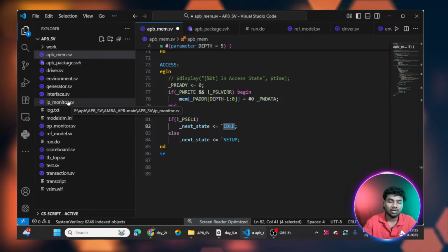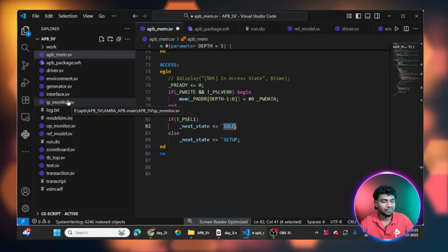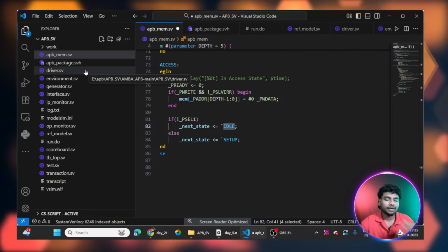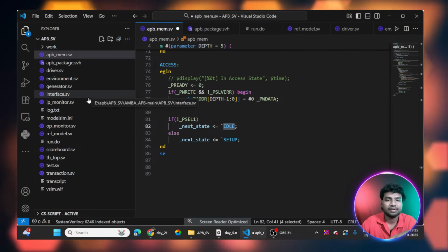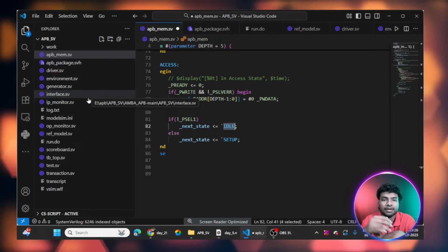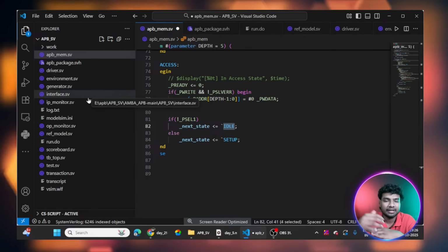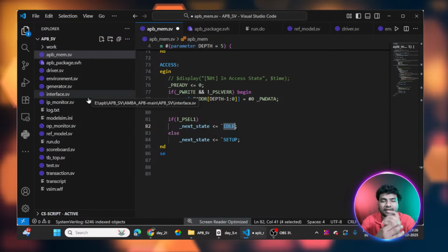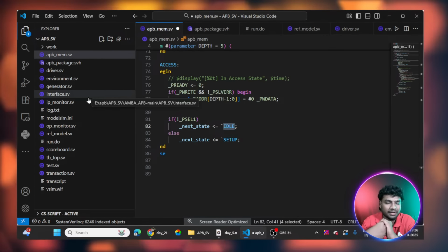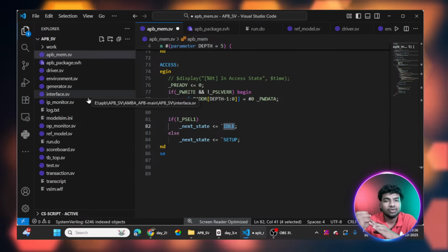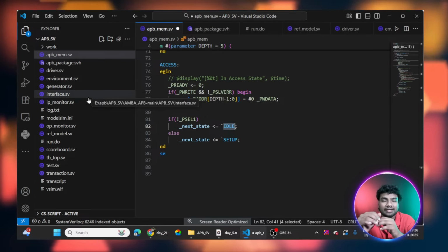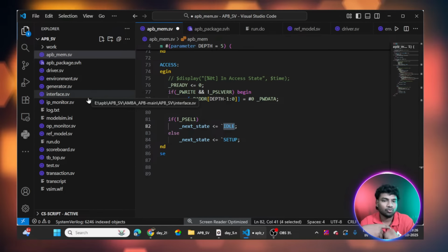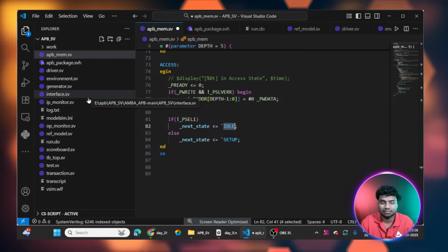Today, till now, we have only seen the design code. Now we are going to see the SystemVerilog test bench architecture for the APB protocol. The test bench architecture has classes like transaction class, driver class, generator class, input monitor, output monitor, scoreboard, environment, test, interface, and design code. We have the DUT, the interface, and the test bench. The test bench classes are dynamic in nature. They do randomization and then transfer into the DUT using the interface. The interface acts like a converter from pin level to packet level and back to pin level data. I hope it's clear for you.